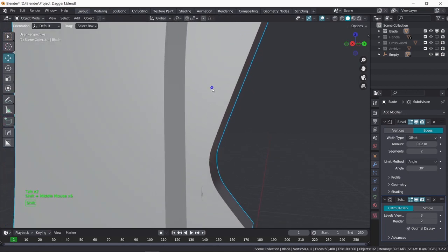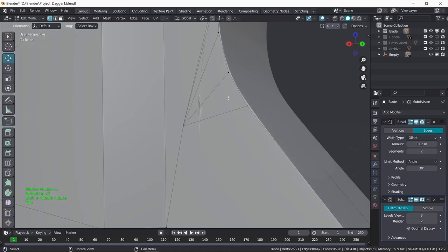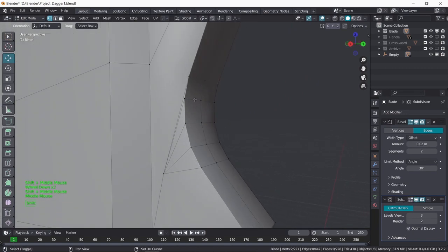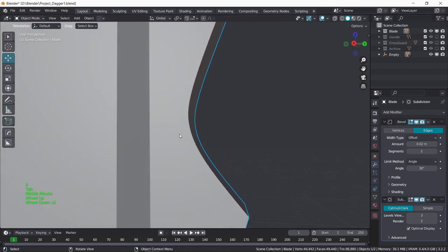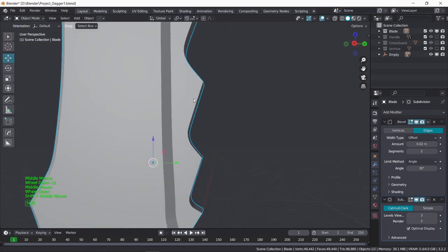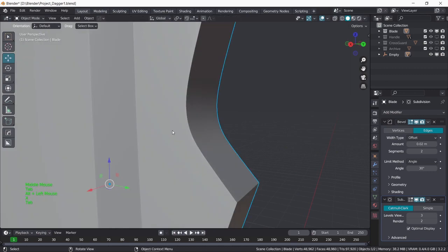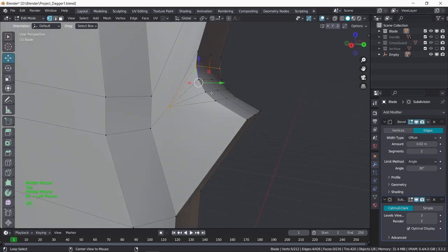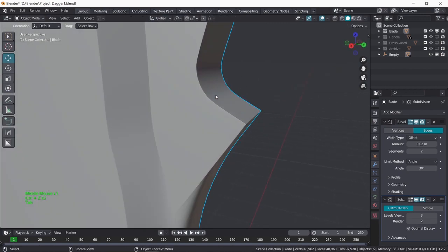So how about we do the same over here, because you can see these artifacts. If we go ahead and remove like 2 of them, how about this one, and this one, then you can see that it's gone, and we still have that nice contour to it. And I think this one's a bit much as well. This one is fine. We can still get rid of 2 of these. Oops. No, that's a bit too harsh. That's fine.